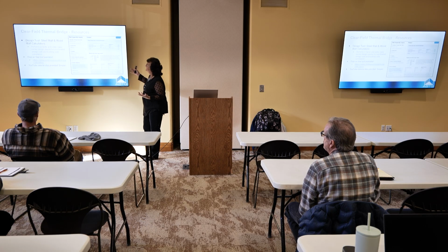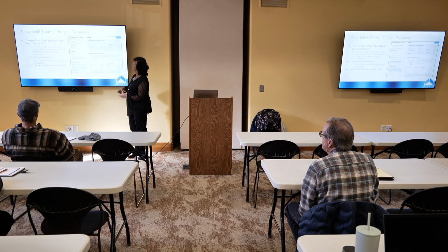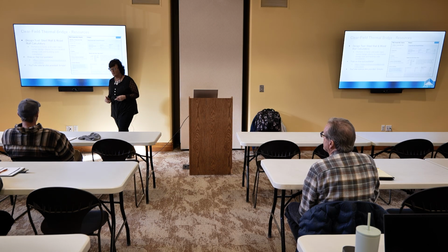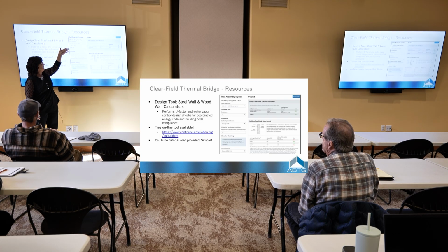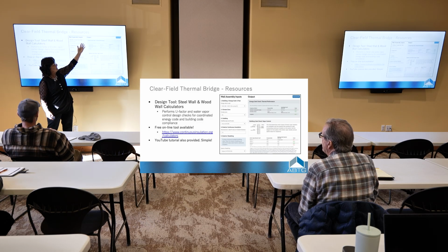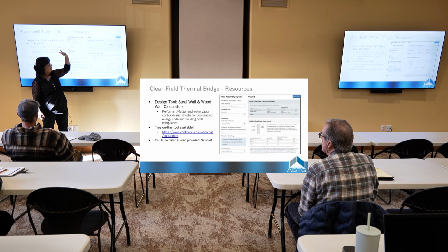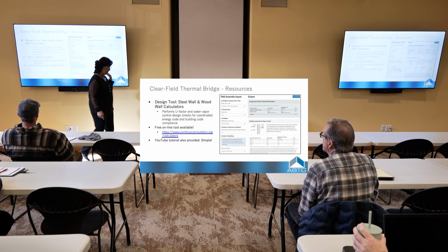This is a great tool on the continuousinsulation.org website. It's called the wood calculator, but it does so much more. You tell it what climate zone you're going to be in, what cladding you're going to put in, what R value you're going to use, how thick your sheathing is. It's going to come up here and tell you, do I comply with code? What do I need to consider on my vapor? Do I need more insulation, less insulation? Where's my dew point? And all kinds of fun stuff. So that's a nice calculator on there.